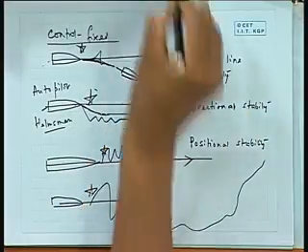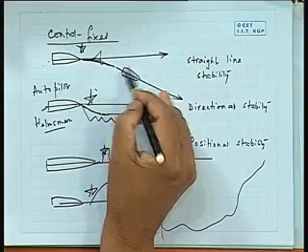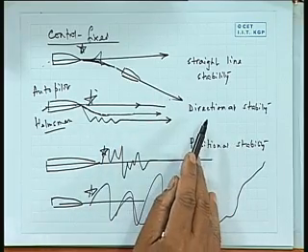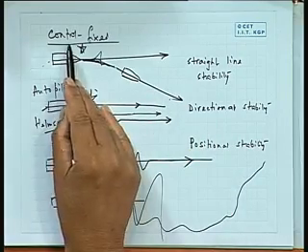That is the best you can have for a ship if you do not give rudder, because obviously when the ship has changed its heading, there is nothing to bring it back. The ship was going on one line, it suddenly takes this angle, you cannot bring it back unless you give a rudder, but at least what happens, it is maintaining this straight line. This is what is called straight line stability, which is control fixed.